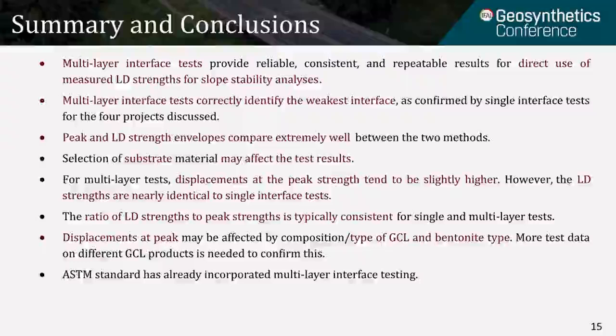Displacements at peak may be affected by composition and type of GCL and bentonite type. More test data on different GCL products is needed to confirm this. ASTM standard has already incorporated multi-layer interface testing as an appendix to their latest update of test method D5321.